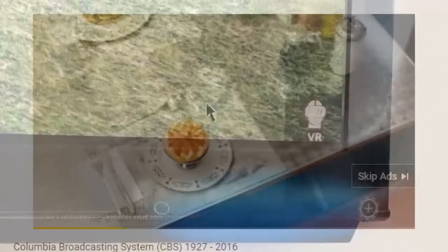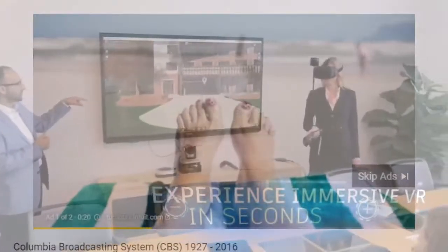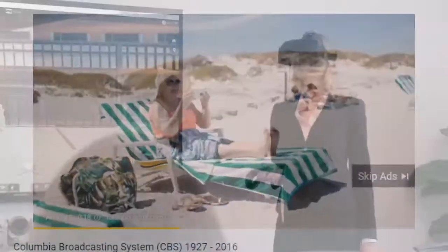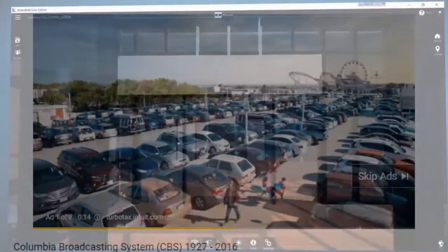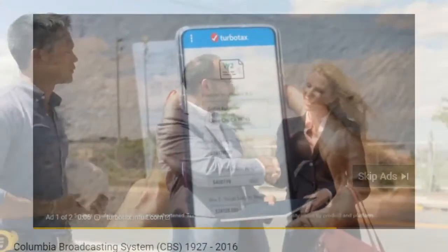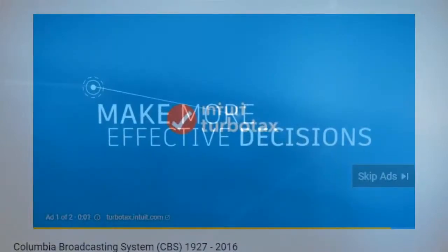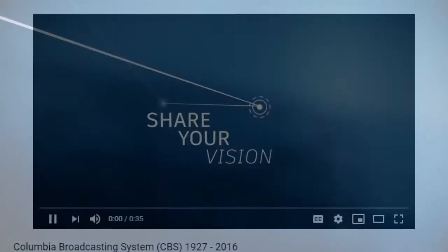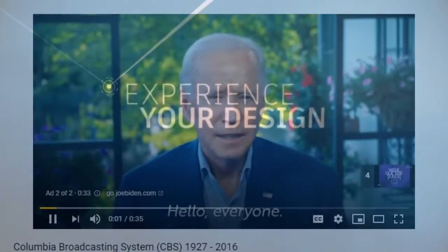Some void forms, if they do not cut anything, will be deleted. To make a void form cut something else, use the Cut Geometry tool. Well, it's not letting us. So, Cut Geometry tool. Select geometry to be cut, the floor. Select void geometry to cut the selected solid. Okay, now let's see if it cuts it. Okay, so you have to actually cut it, it won't cut automatically.